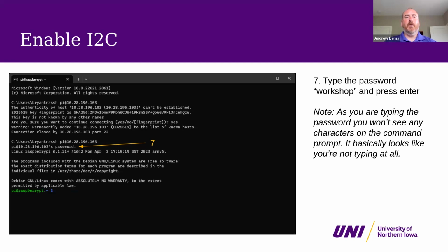All right, so we've installed Raspberry Pi OS. We are now connected over Secure Shell, or SSH. We are now connected to the Raspberry Pi remotely. Again, at this point, you can remove the HDMI plug and the USB plug that ran the keyboard and mouse for you. Leave in, obviously, the power plug to keep the Pi running.